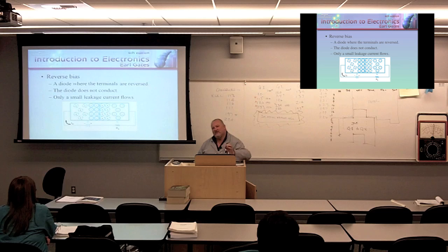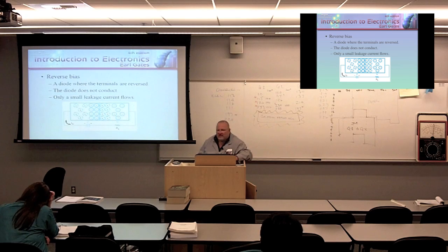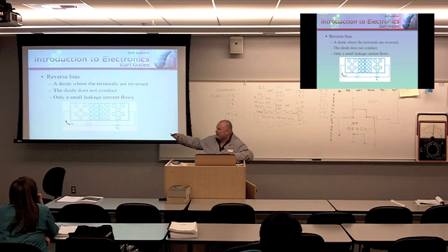Now I crank it all the way up to 75 volts. Well, this diode, let's say, is only rated to go as high as 35 volts reverse voltage. So as soon as I get up to 35 volts, this depletion region gets so big that current is just going to arc through it, and it will destroy the diode. So all diodes are not created equal.